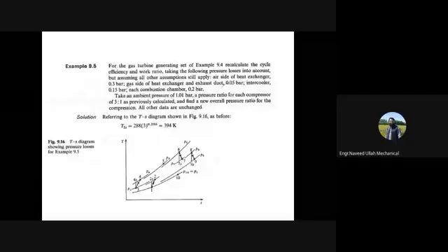उसके पास ये जो एग्जांपल 9.5 है, यहाँ हम लॉसेस को करते हैं कि आपके पास एग्जॉस्ट है, उसमें लॉसेस कितनी है, प्रेशर लॉसेस, अच्छा इन बार्स, इंटरकूलर में कितनी लॉसेस हैं, कंबशन चेंबर, इस तरह ये सारे लॉसेस को कंसीडर करते हैं। Instead of having constant pressure lines, we are basically having a break between these two, ये बेसिकली लॉसेस हैं। हम कहते हैं ना कि हमारे पास कांस्टेंट प्रेशर के ऊपर हीट एडिशन होती है, right. यहाँ पे कांस्टेंट प्रेशर नहीं है, बल्कि you can see there is a pressure loss, यहाँ पे प्रेशर लॉस है छोटा सा, similarly यहाँ पे प्रेशर लॉस है यहाँ पे।